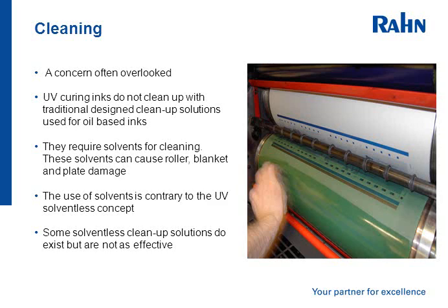So a further word on cleaning, which is often overlooked. UV curing inks do not clean up with traditional cleanup solutions used for oil-based inks. They require solvents for cleaning, and these solvents can damage blankets or rollers or plate. Again, you can achieve solvent mixes which give good cleanup and minimize the possibility of damage to these elements. Also on the market, there are some solventless cleanup solutions. They work, but they are not as effective as the solvent-based systems.